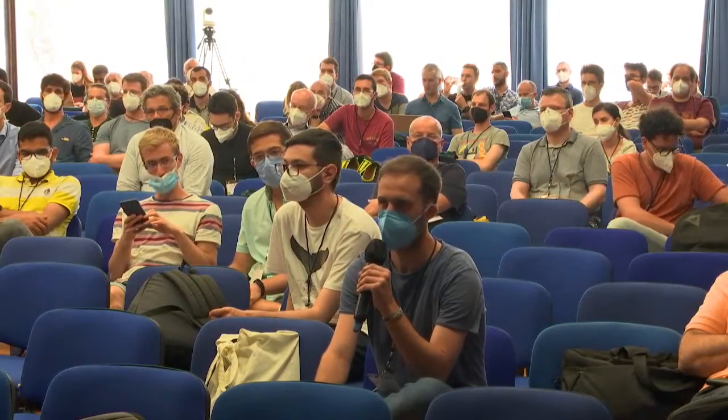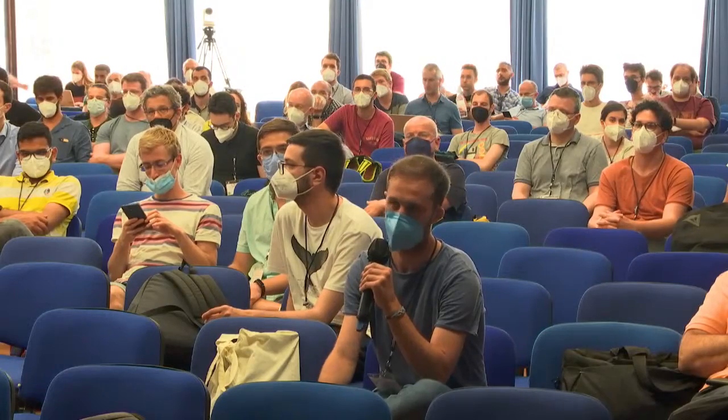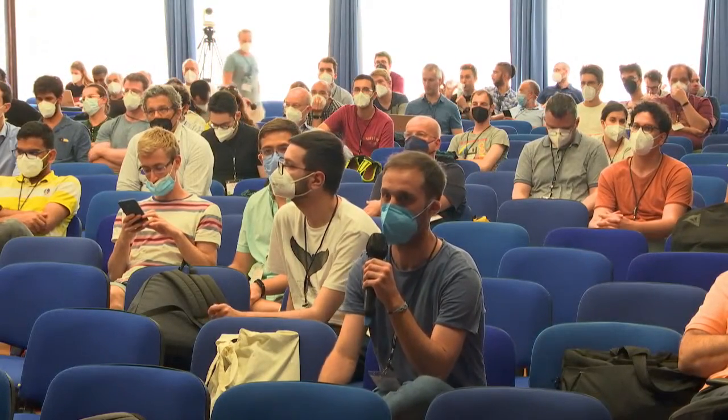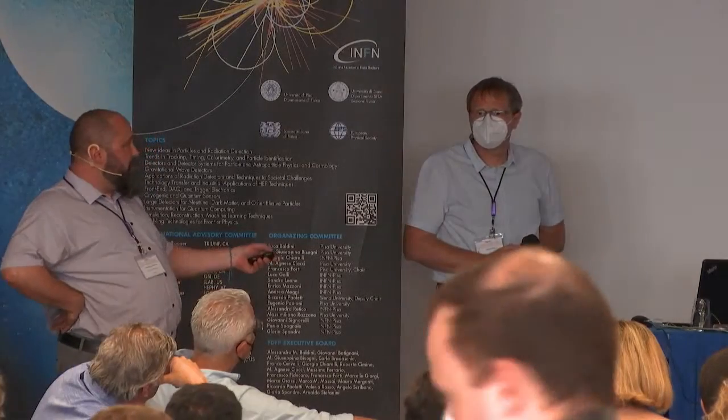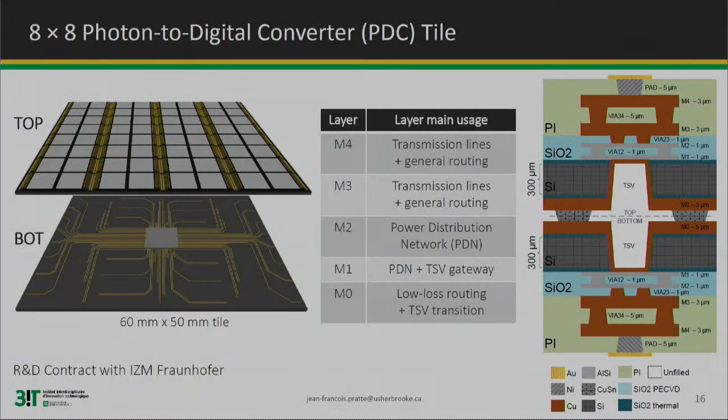Can you please comment on the fill factor you are achieving now, or what you expect to achieve, because you were talking about that. It's not going to be very high. If you think about each of these gray chips, they are 5.3 by 5.85 millimeter with an active area of 5 by 5 millimeter square. And we are accounting for about, I think, something like 2 millimeter between rows for wire bonding. I don't have the final number in my head right now. I can get that to you. I know we also have this number somewhere. But yes, that's why I want to put TSVs in the CMOS so we can get rid of all these wire bonds and make it way tighter.